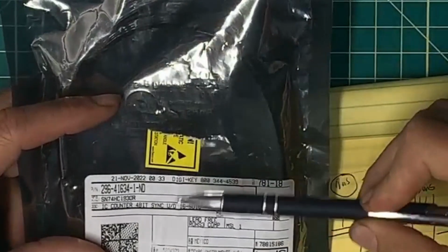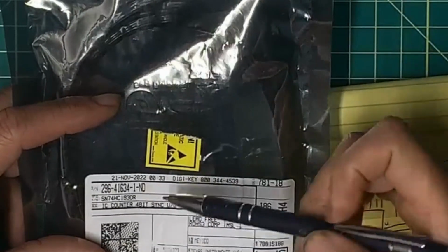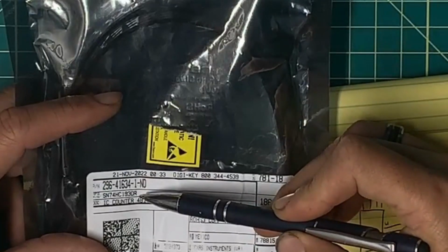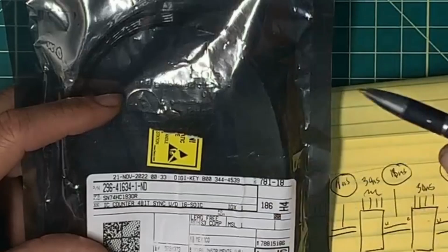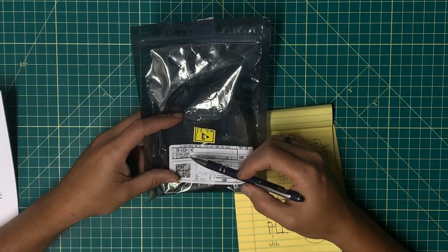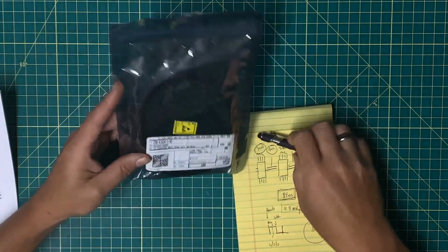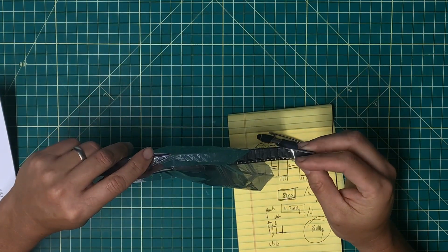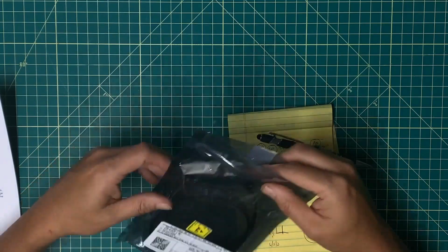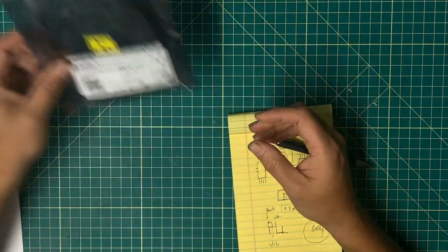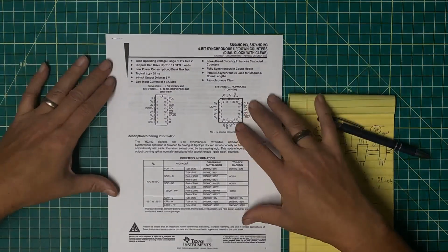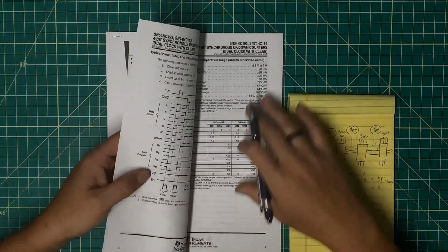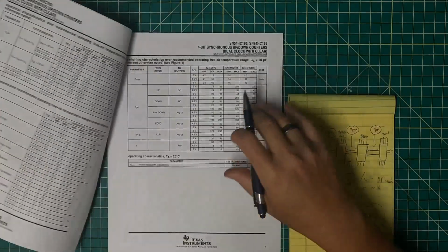These are the ICs I've been using in my build so far. So these are Texas Instruments SN74HC193DR. Now DR, part of that indicates the packaging, and it means that they're on tape, and basically I just pull them out individually from here, turn around and solder them onto the board. Now, I also pulled the datasheet for these. And these are not quite as robust as I thought that they would be. So let's take a look here.